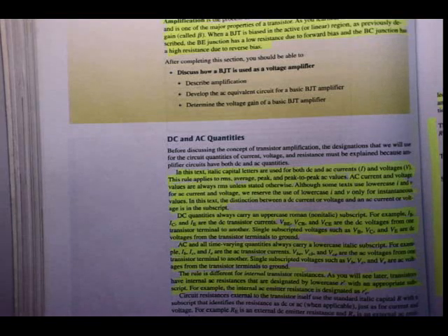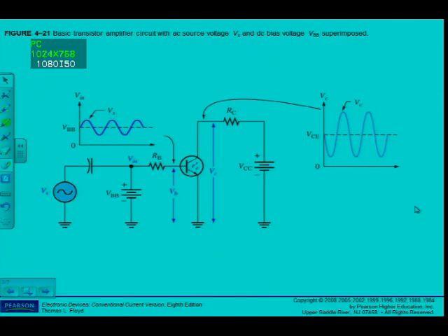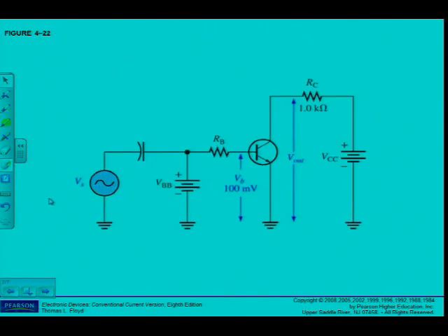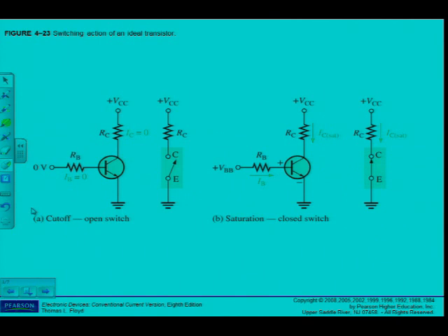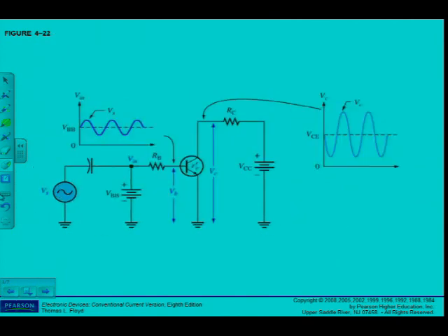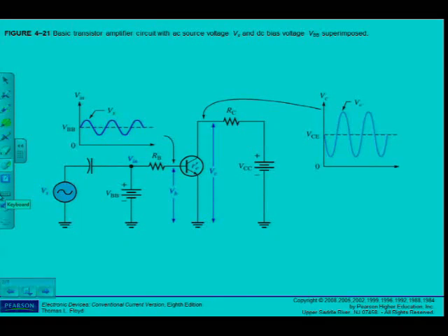So if you are given a voltage as, say, a source voltage, if I go and look here at the specific diagram, you have to go and calculate, for instance, a source voltage was here given as say 10 millivolts. So it was given there as 10 millivolts. I immediately know that if there's nothing mentioned, this is an RMS value.